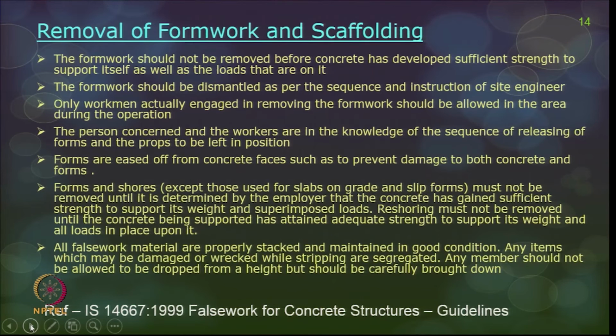And here also there is a life cycle of repetition for reusage. So, that also should be kept in mind, and accordingly the shoring and reshoring process will continue, and this formwork can be used for the floor above and so on. That should be borne in mind when you are planning for the formwork life cycle and the schedule of your construction.